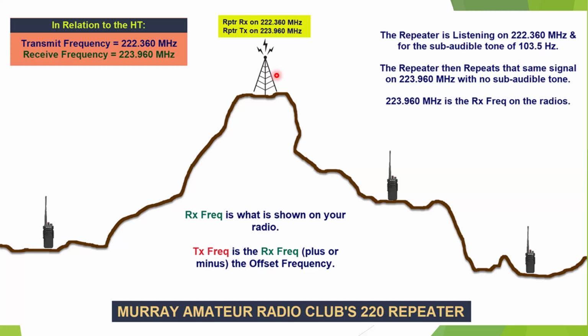Our repeater is listening to your radio on frequency 222.36. And not only that, but he's also listening for a subaudible tone of 103.5 hertz. So during the nets and during all the communication that we do, we always include the PL tone, right? Because that's also required. And we're going to talk about why that is so important.